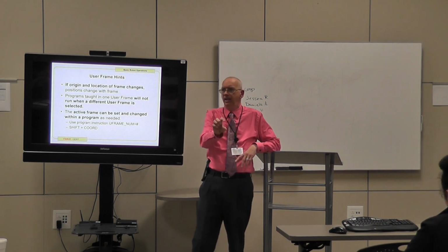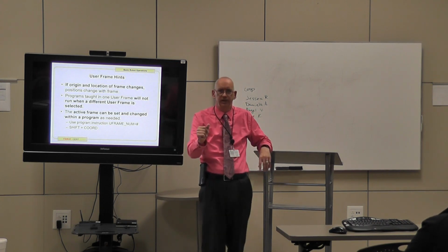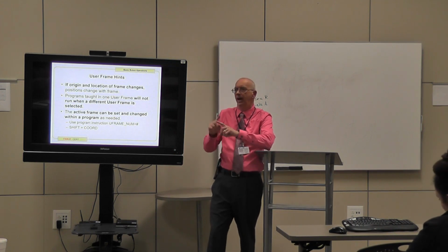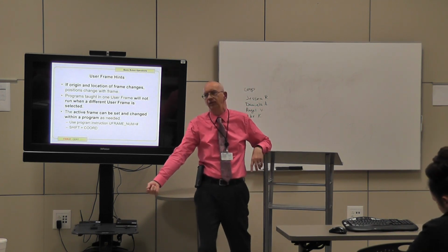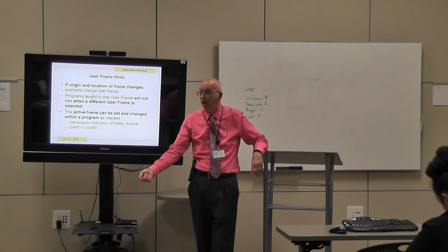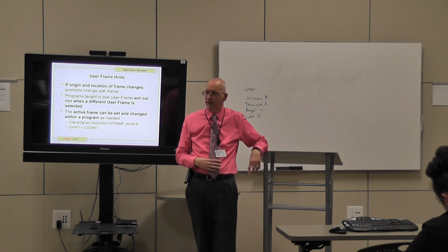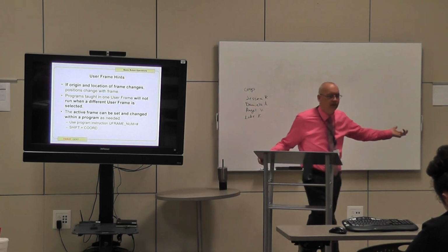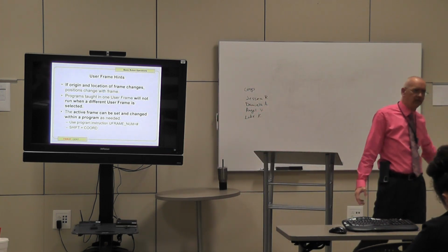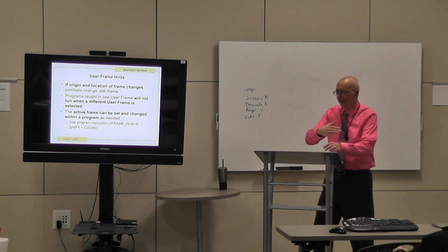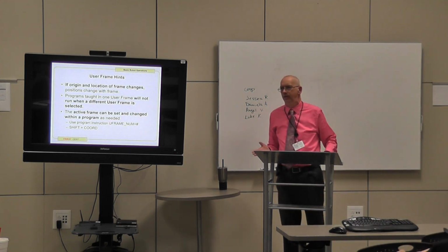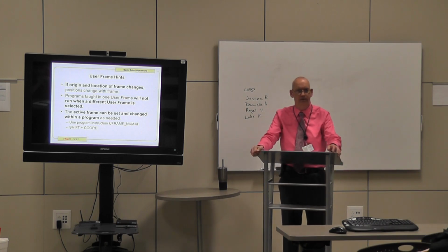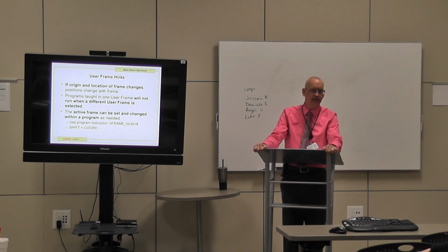So if you assign it in your program, what it does is it changes your user frame while you're in your program. In other words, you do not have to go and change your user frame when you're running it in auto. It's going to change it for you inside your program. Okay, so if you're in user frame 17, because you have 17 different defined user frames, well, when you bring your program up and you run that program, boom, it's going to automatically go in the frame it needs to. Any questions on that?